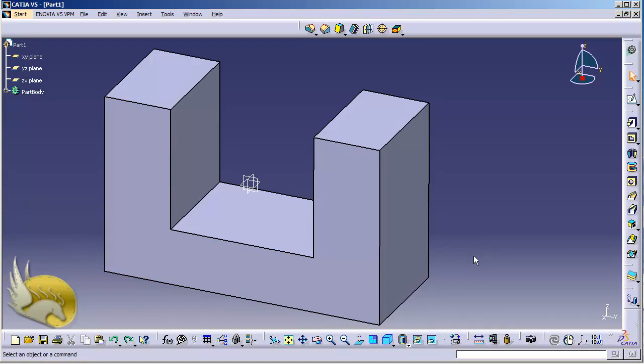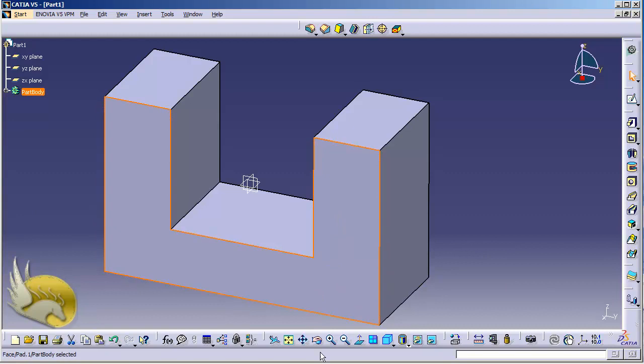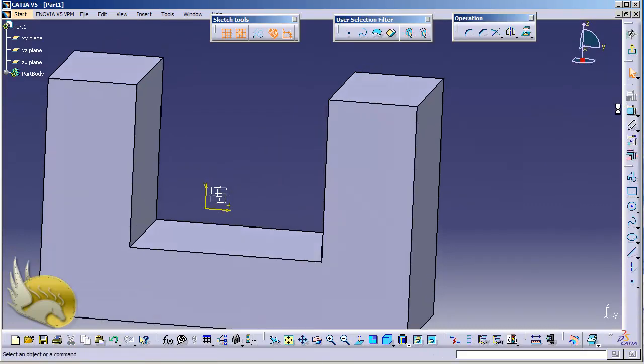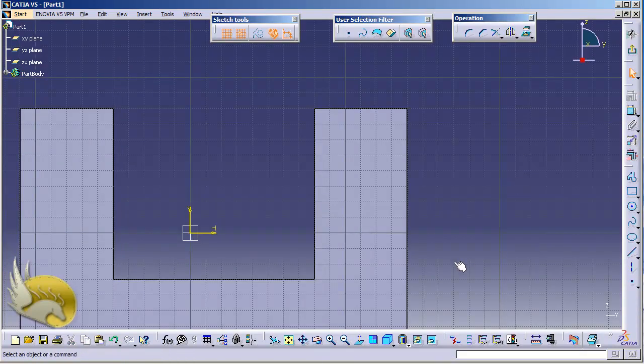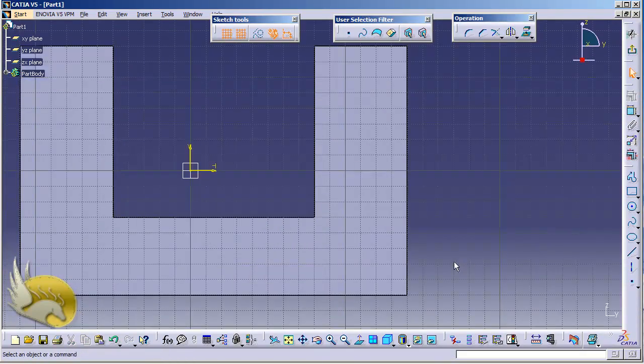So first of all, I want to create some points and show you how you can change the fillet in that point. So I'm going to add 3 points, for example, to this edge. I guess this edge is okay. So I click on this face, I go to sketch, and now I'm aligned to this view. I'm adding some points here, so I go to profile and add some points. For example, the first one is going to be here, the second one is going to be here, and third one is going to be here.